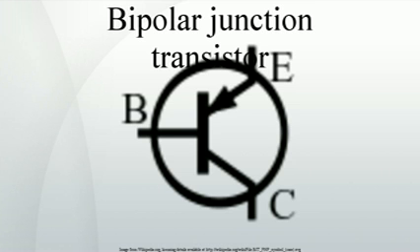The grading of composition in the base, for example, by progressively increasing the amount of germanium in the SiGe transistor, causes a gradient in band gap in the neutral base, denoted in the figure by ΔΦg, providing a built-in field that assists electron transport across the base.